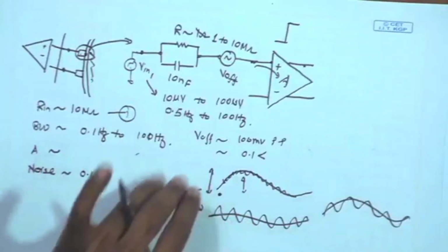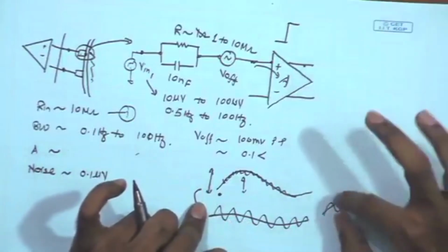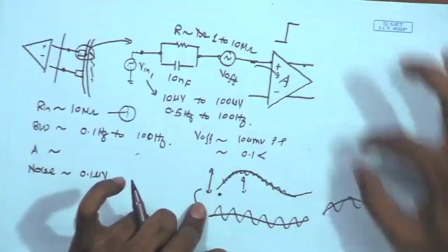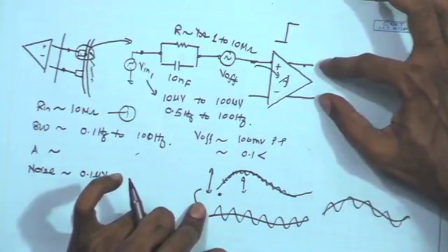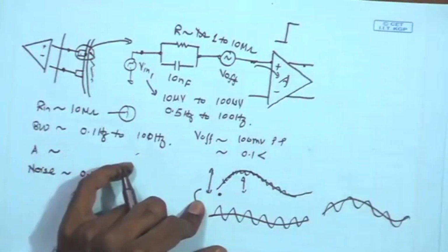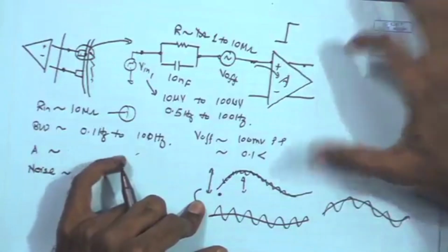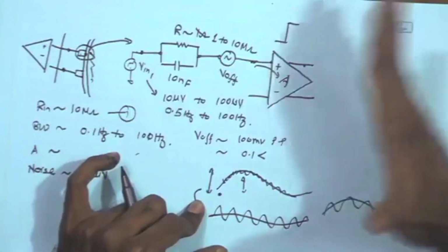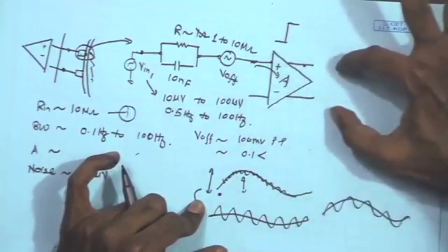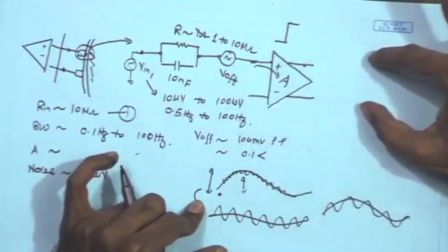For that I will keep an assumption that my desired signal is magnified at the max, say to 100 millivolt before it goes to the ADC. So, before the signal reaches the ADC it has to be amplified to the maximum extent, so that the ADC can get the maximum amplified process signal.